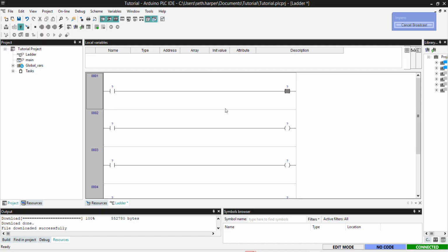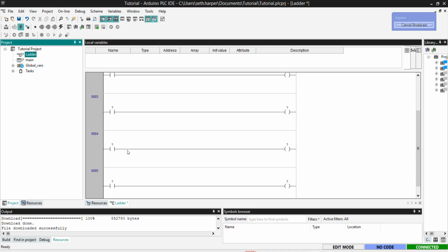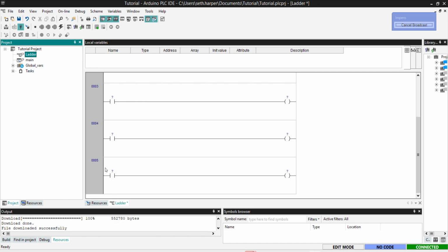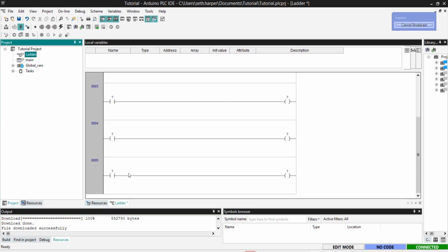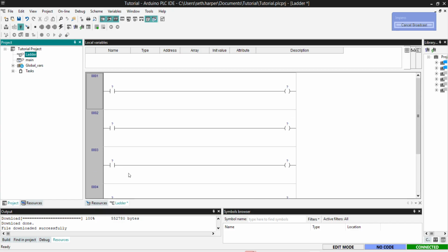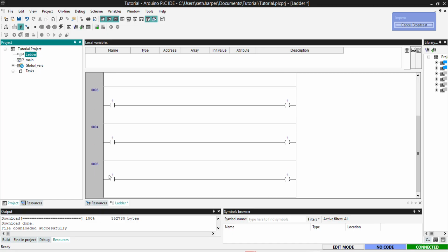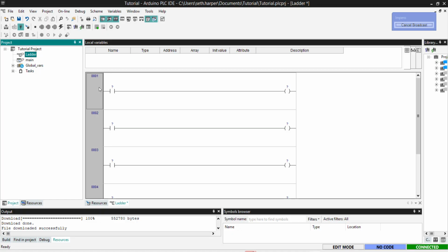Now, what happens with ladder logic is it executes the program within milliseconds, but it does it from top to bottom. That's probably not going to be super important for anything we're doing. But if you are referencing things that are functioning on a very fast level, and this changes down here, but it's called up here, then it might not actually execute immediately.